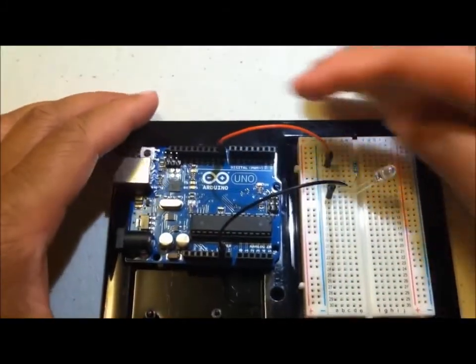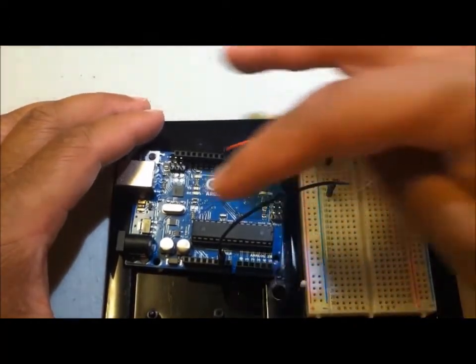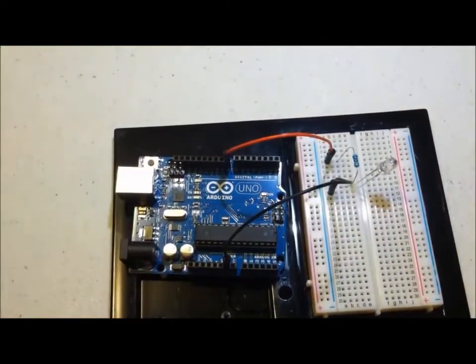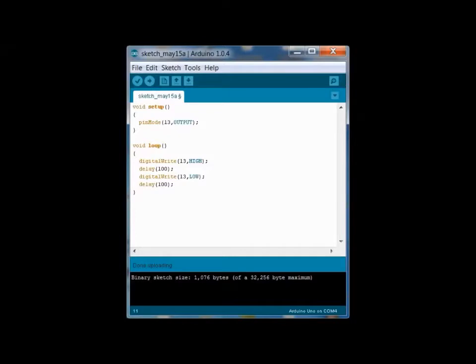Alright, there we go. So as you can see, we have a complete circuit, coming in, going through, and out, and back again. The only thing we have to change in our code is changing 13 to 8, because we changed the pin reference. All the points where you see 13, it's still going to be output because it's outputting information. And we're still using digitalWrite because we're still using digital pins, which are here. So we're going to change all places we have 13 to 8.